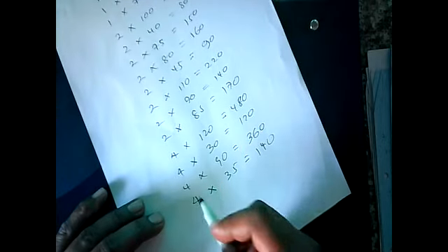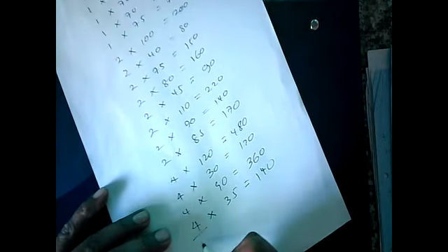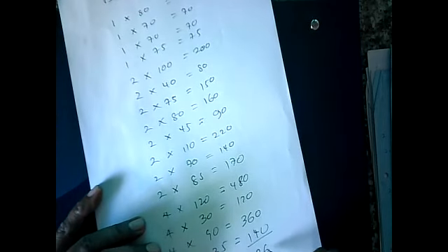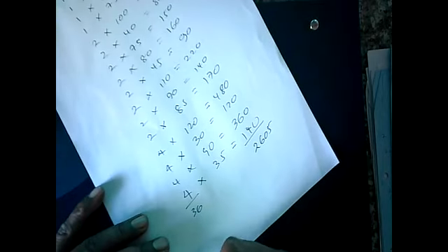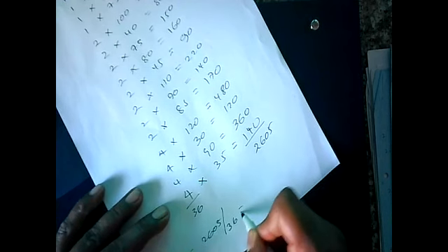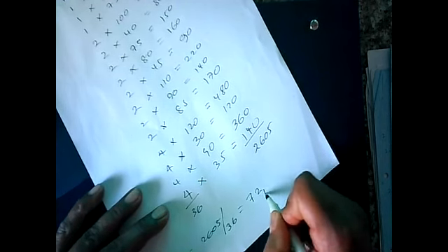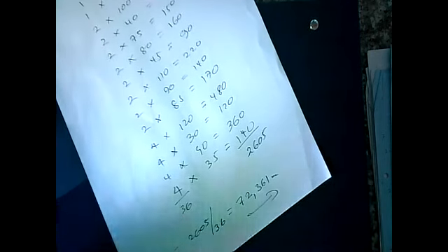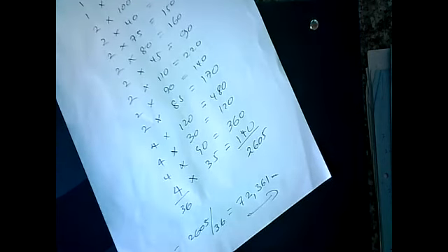All right, now let's complete it to find the average of this. Tally all the weights up and you get 36. Tally all the weighted levels up, you should get 2605. Right? And 2605 over 36 gives me 72.361 meters. And that is our average level.